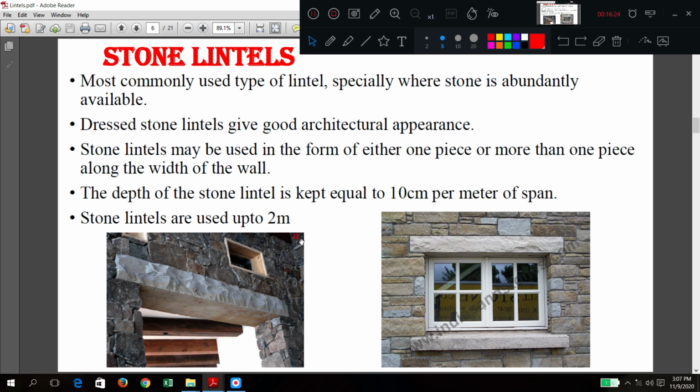So just enlarge. Now this is the span. Do you agree? What they are telling is that the bearing should be at least 1/12 of this span. It should be provided like this. Height, at least it should be equal to the height, h equal to b. At least the bearing should be equal to its height, means this and this should be the same. At least means for stronger masonry work, it should be at least 10 centimeter. Any of the three criteria should be met.